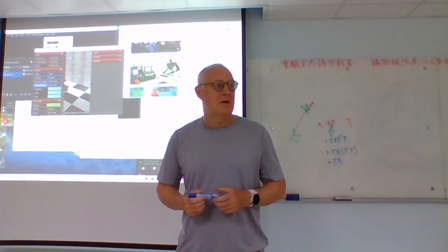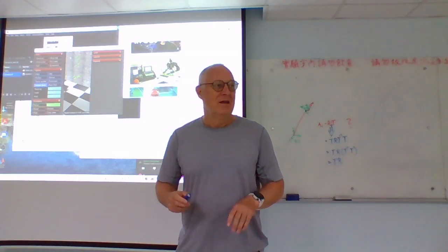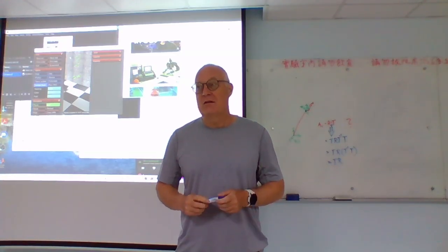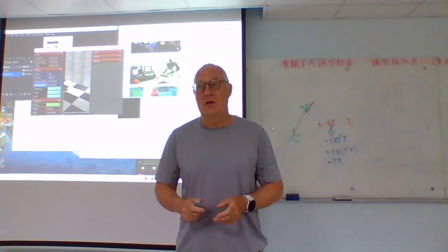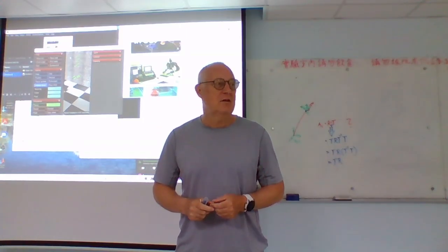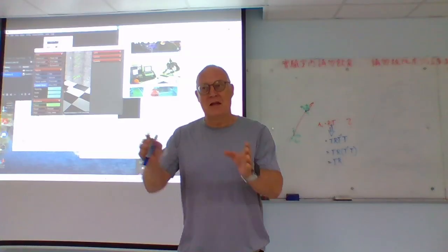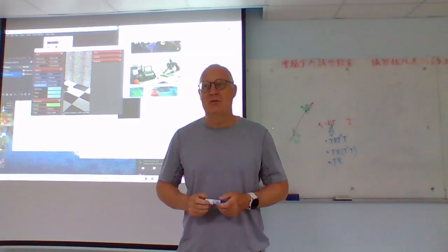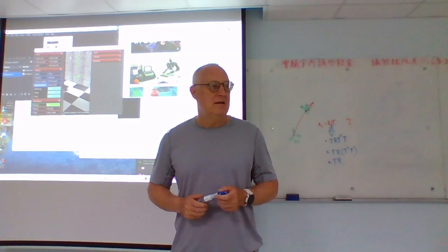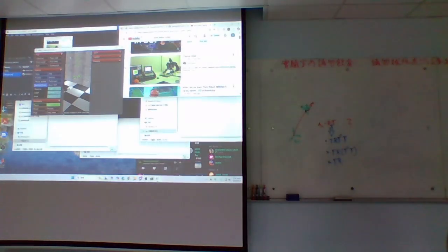Because from the Blender software, I can get the position difference between the bodies, because I need to place the bodies and the joints. So I can figure out what the translation vector is, and I know what the rotations are. Otherwise, Blender couldn't draw it; it also needs the forward kinematics in order to draw it properly. So my idea was to add that into the Blender program, and that usually works really well.